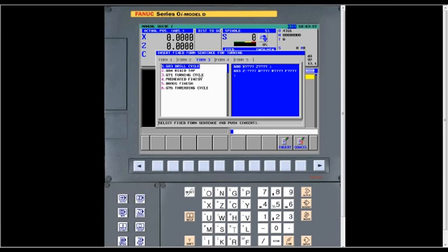And number 3, I've got drill cycles, tapping cycles, turning cycles, threading cycles, where if I don't want to use the cycles within Manual Guide I, I can just go use these, just paste them in. Form 4, I've got calling up a subroutine, or a G10 assigned value type of thing, or just starting a spindle. Form 5 is just end the program.